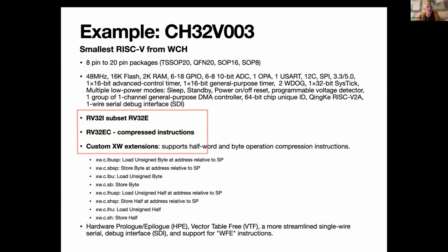If you buy an off-the-shelf analog to digital converter, even a low bit one might cost you 50 cents off DigiKey. This thing's got 6 to 8 channels of a 10-bit ADC, so you might be able to use it as an I/O peripheral. And this is part of what Peter Jackety and I have been talking about: using this type of small core as a universal peripheral, but have it talk Forth so it's programmable. So it's a programmable I/O processor.